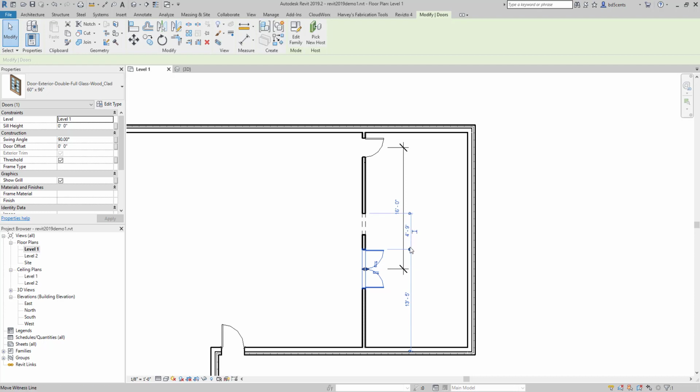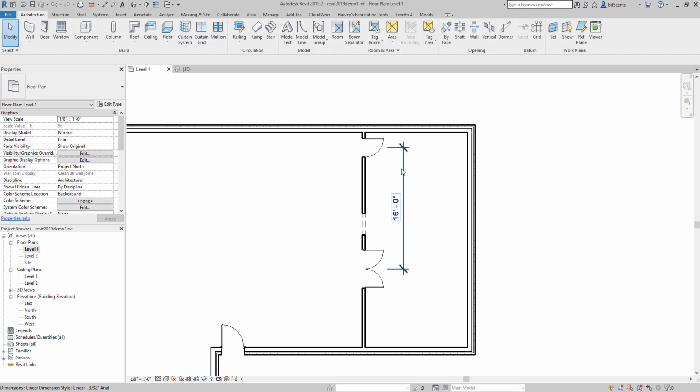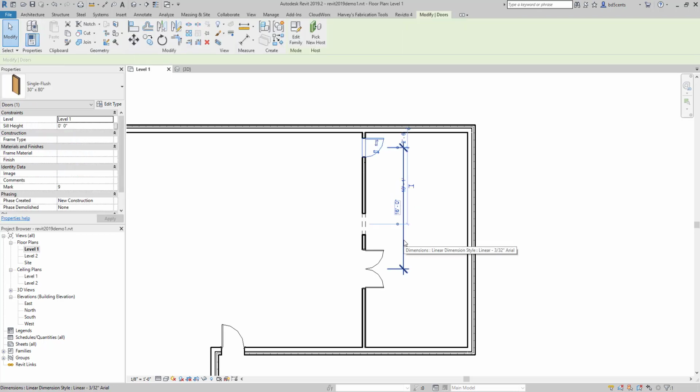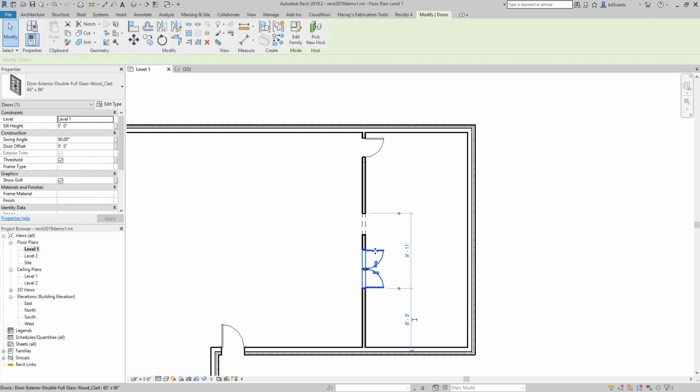So you'll notice as I'm clicking on that dot, it's going to adjust those values of those dimensions to get what I'm looking for. Same thing here. If I select this dot, it's going to adjust to the outside, to the other one, to this center of that door. I drew this dimension just to ensure that I had that value locked in. So I made those 16 feet away. Note that whatever door you want to move, you're going to highlight that door and then change the dimension that you want to move. The object you pick is the one that moves.